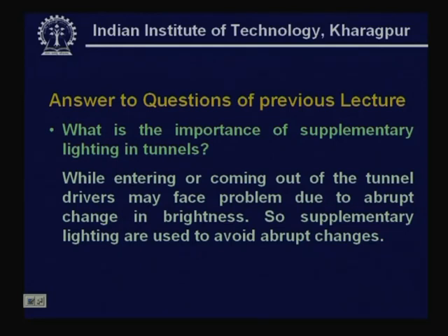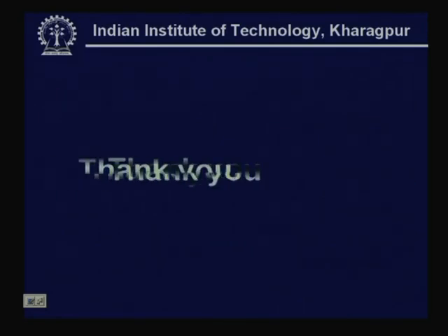What is the importance of supplementary lighting in tunnels? Some tunnels, depending on the length, as we said, have a number of zones. So, one has to be careful that gradually the user is adapted to the light levels outside and inside. Therefore, supplementary lighting is necessary to avoid abrupt changes. In fact, some supplemental lighting at increased levels is necessary during the daytime more than the night time. This applies even to closed corridors for interior lighting. Thank you.